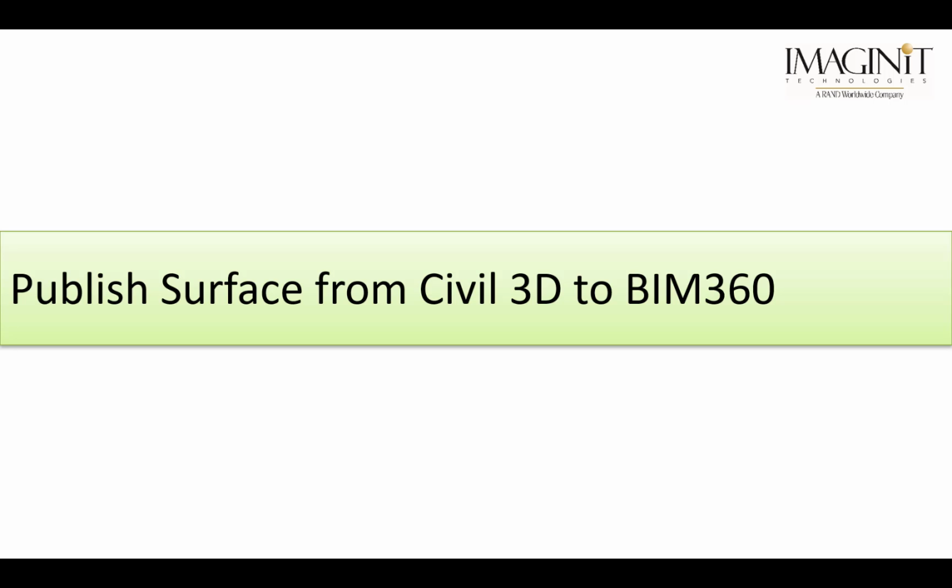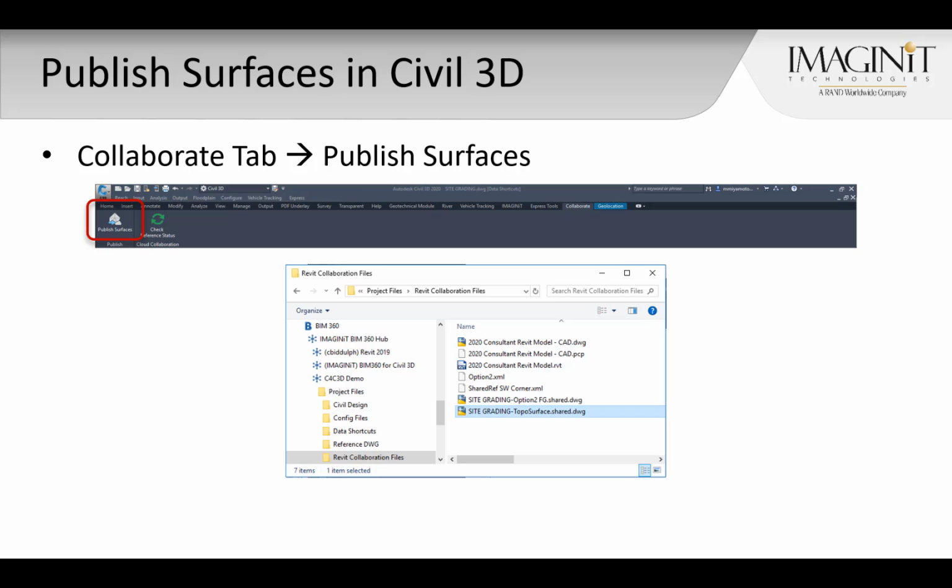A major benefit of this feature is the automatic placement of a topo surface linked to the Revit model. In order to link a topo surface in Revit, a shared file needs to be published to BIM 360 from Civil 3D. The BIM 360 functionality within Civil 3D allows us to publish a Civil 3D surface directly to BIM 360 docs, where a Revit-compatible shared file is produced. The Publish Surface command is located on the Collaborate tab in Civil 3D and generates a shared DWG surface file in a designated BIM 360 docs folder.